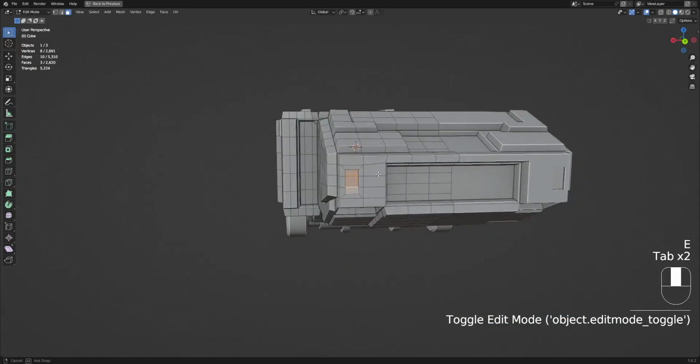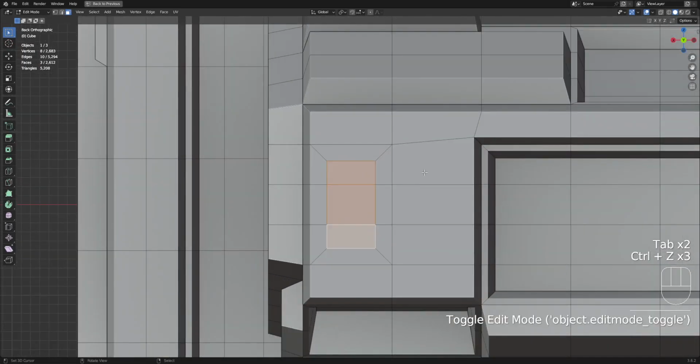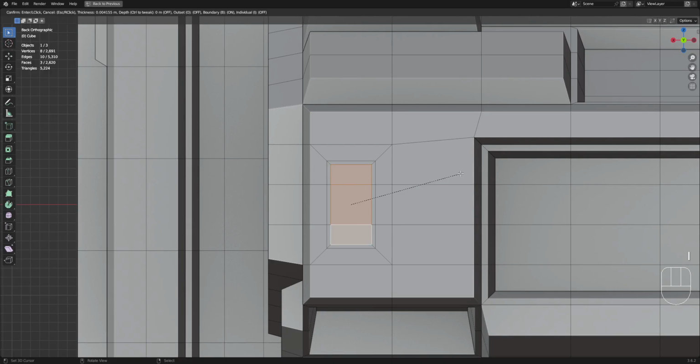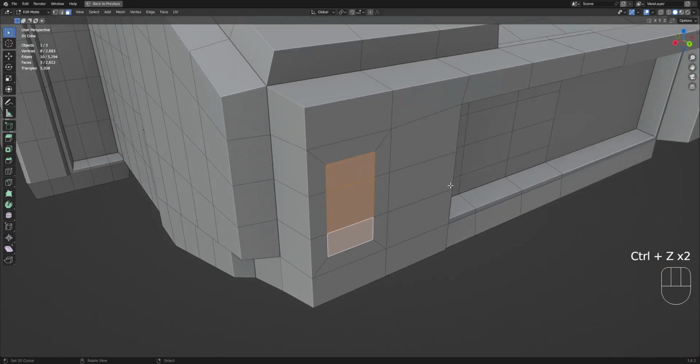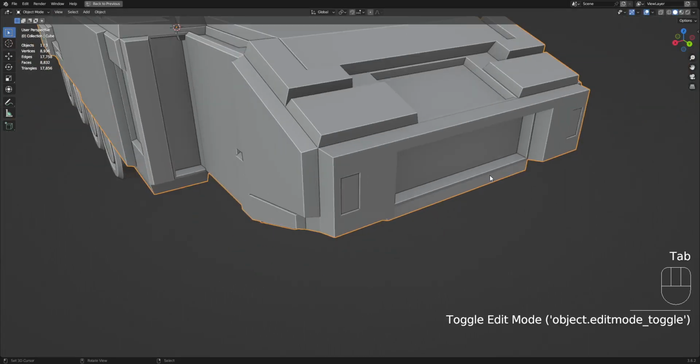So you see it's gonna be flat. So in order for the detail to be more obvious to the eye, and even if you want to bake it, you can just use inset and give it a little margin. During inset, you can press I, then drag the mouse to increase the margin, and then press control and drag the mouse to offset the faces, and like that.